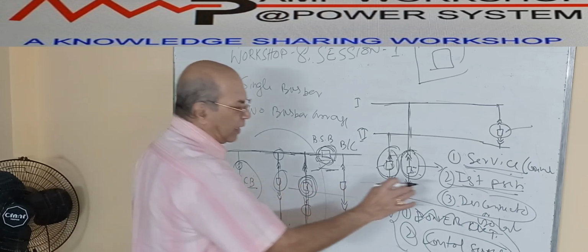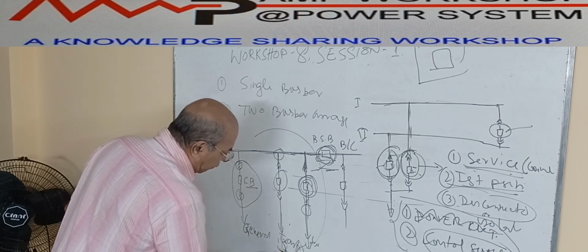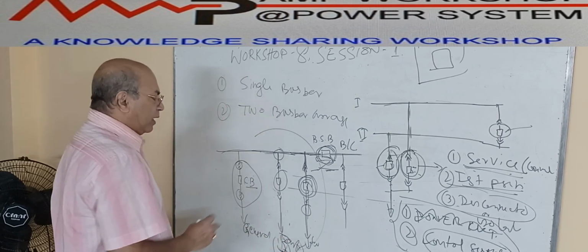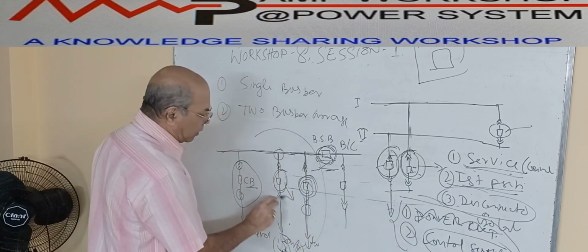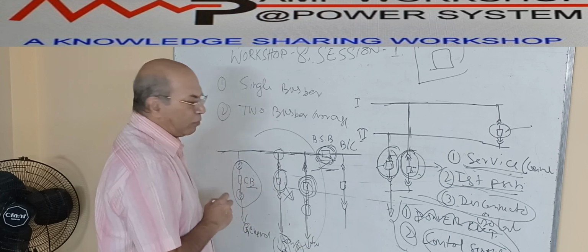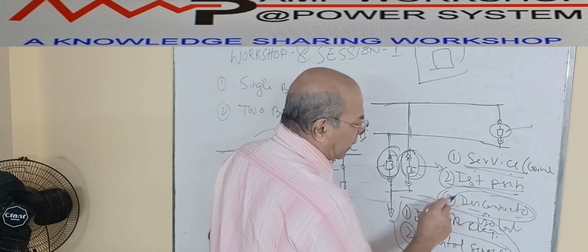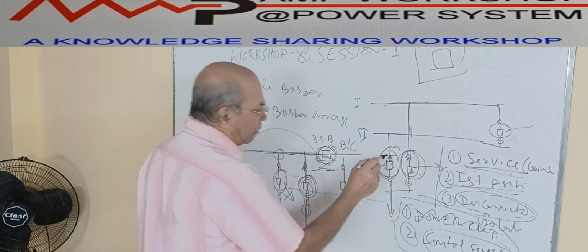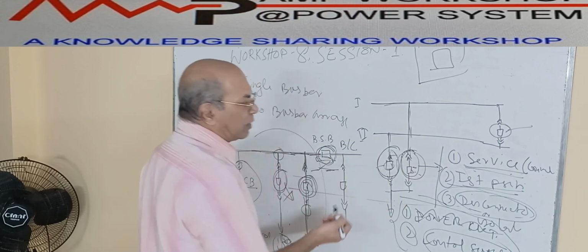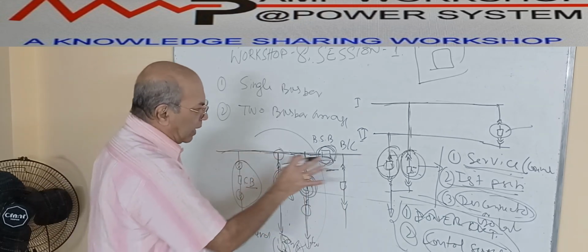When we take the disconnected position, suppose there is a transformer over here, we need to maintain the transformer. In that case we take this breaker to the disconnected position and we put a lock, so that nobody can open this lock and close this breaker. So these are the requirements of the disconnected position. These are the three positions, and with the drawout arrangement, we can take out the breaker in these three positions one after another if we need. So this is the arrangement.